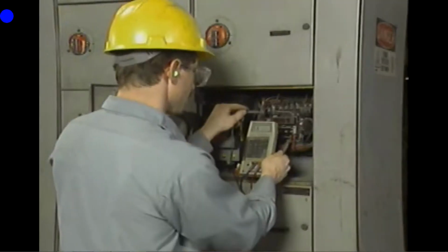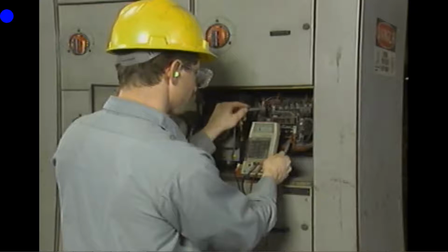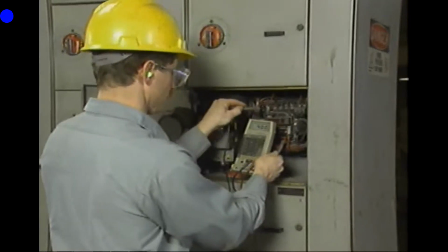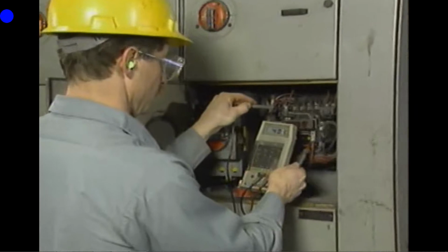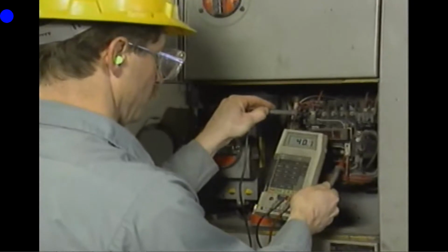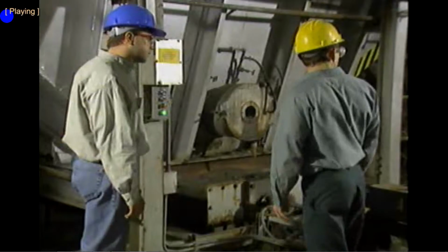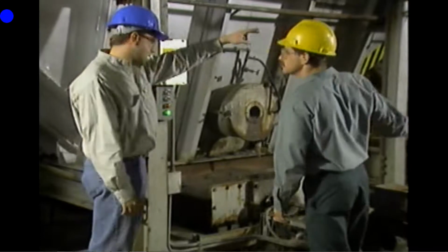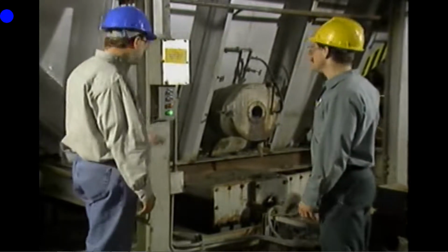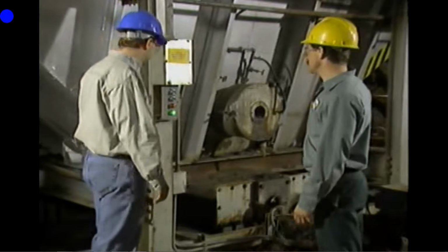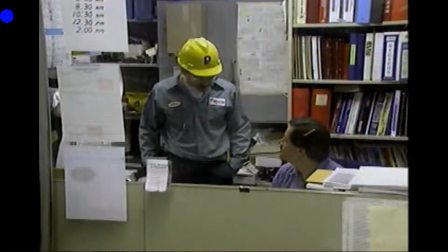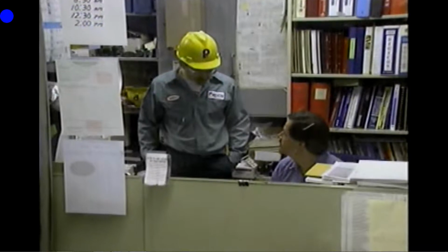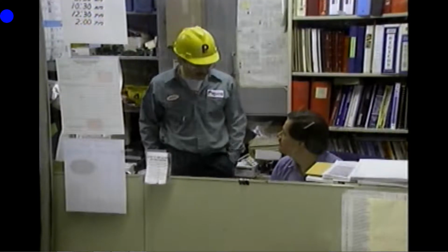Once you know how the controller should operate, you can investigate how the controller is actually operating during the malfunction. To do this, you have to identify the symptoms of the problem and then decide what to do about them. The operator who reported the problem is often the best source of information about the problem's symptoms. This person can most likely give you a clear description of what's going on. If this person is not available, you might be able to talk to the supervisor who received the trouble report, or read the trouble report yourself.